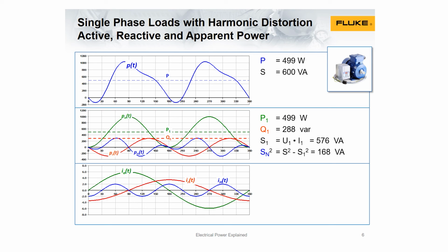Currents. Once we split out the powers, we can calculate the values of all three currents. The 5 amp now separates out into the 4.157 amp active, 2.4 amp reactive, and 1.4 amp harmonic. Because it's calculated using the vector sum, the wasted current is larger than you'd think for a relatively small difference between 5 amp and 4.157 amp.